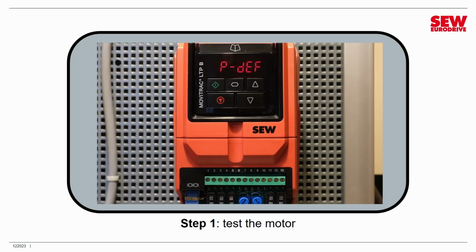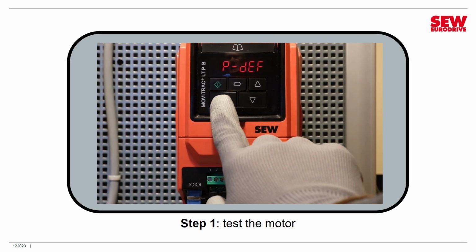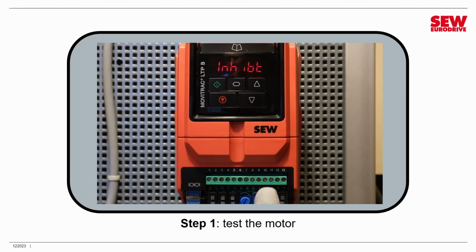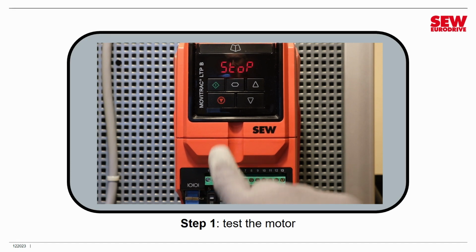All right, our VFD is showing PDEF. That's because we factory defaulted it. So the first thing we have to do is just clear the message by pressing the stop button. So we'll do that. Now we're in controller inhibit, so I have to remove safe torque off by turning the 2 safe torque off switches on, and then I turn digital input 1 on to enable the VFD.